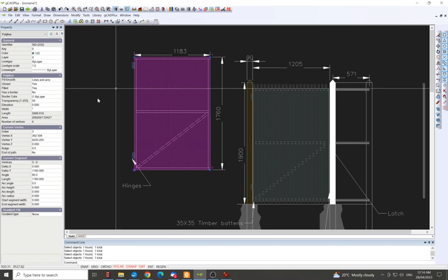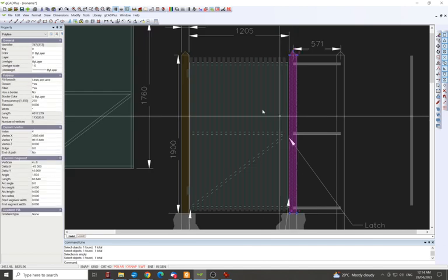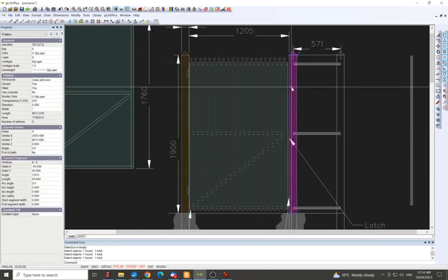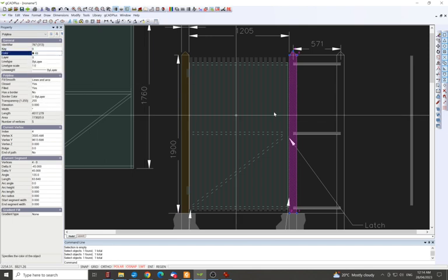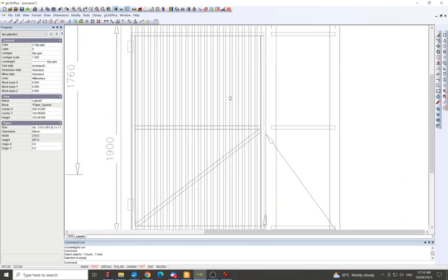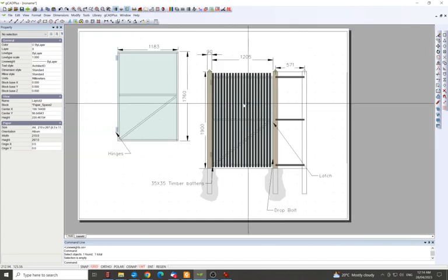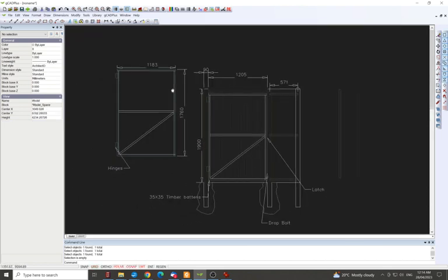So you can manipulate, you can see transparencies, color, line weights. If there's a line it has a border, etc. There's heaps of little things you can work out with it. And what's good about that is I can grab this one here. We can see what color that is. Click this one now. Color by layer, but we want to go to 48. We know the transparency was 100. And now we've got two nice posts. These posts are actually black, but to distinguish them from the gate and the other parts I'm just going to do them that way. So we'll give him a bit more detail too.